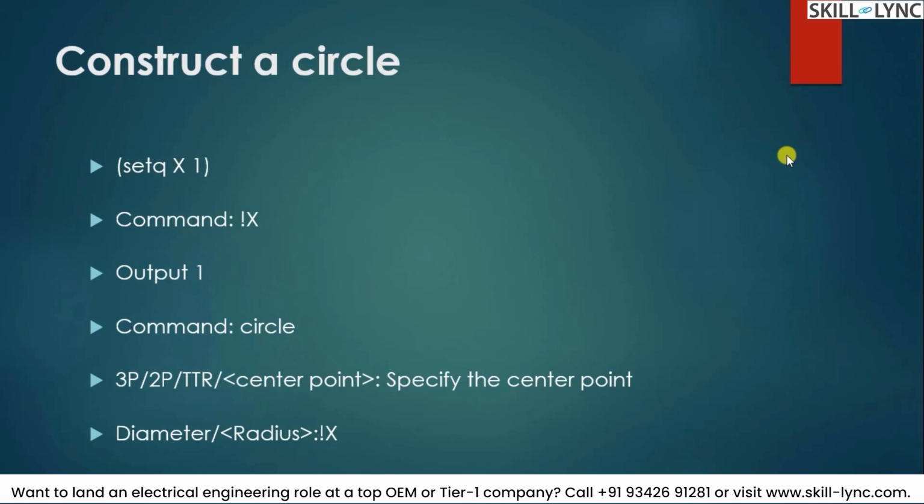So when we are calling for that as an exclamatory x, now it will result in a radius of x for this point. Also, you can recollect that whatever is inside the angular bracket is the predefined command here. So this x is assigned as a radius to the circle that we have here. So this is how you can call for the input, a numerical input, by a pre-stored value using AutoLISP function.